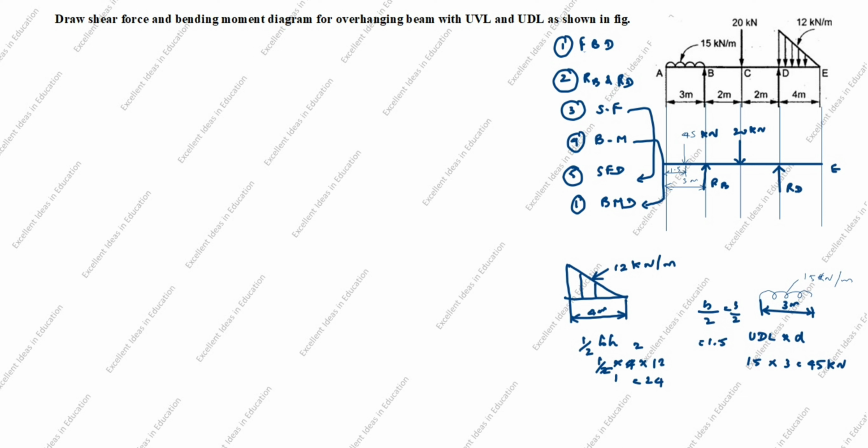kilonewton. You see here, this is 90 degree, right angle is here. From here to here only we will calculate distance. This distance is B by 3. What is B value here? B is 4. 4 divided by 3 equal to 1.33. So this distance is 1.33. So what is this distance? This distance is 2.67. The whole is 4 meter.